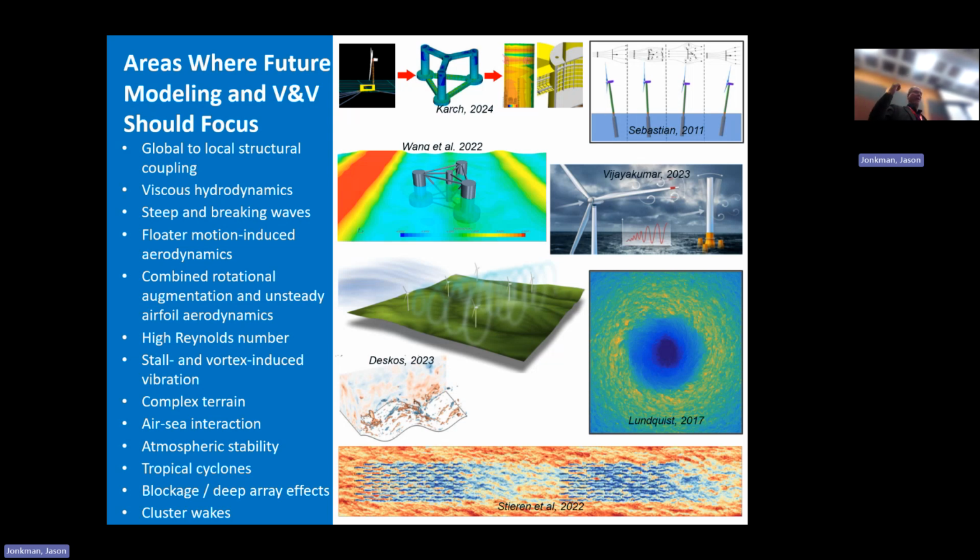I've been trying to get funding for a while. I think we have some good leads now. How to get from global, so OpenFAST generates shear forces and moments, but at the end of the day, for my floater, I want stress and strain in each one of those, the scantling of the components of my floater. And so definitely a strong industry need there if you're doing detailed design of the structure. And so we have partnerships we're making to make sure that's a seamless coupling between OpenFAST and the FEA solvers.